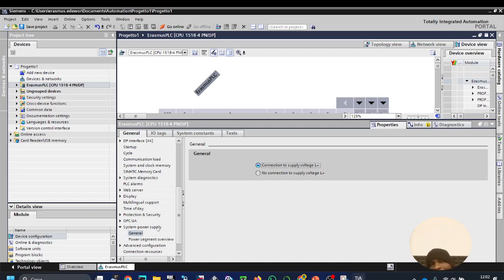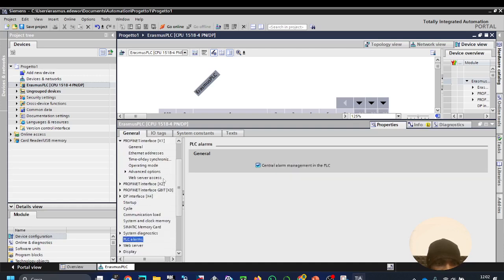But below 23, if you have like 22, 21 volts, it becomes a little problem for the PLC. So it's always better from 23 to 26, you know. All right. Okay, I think that is cool for now.